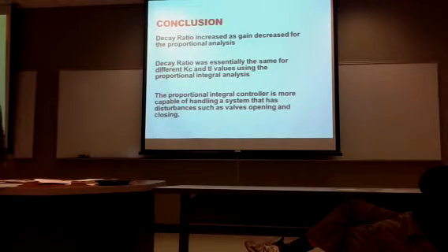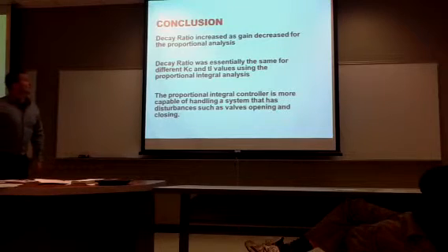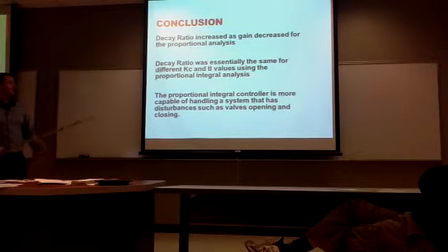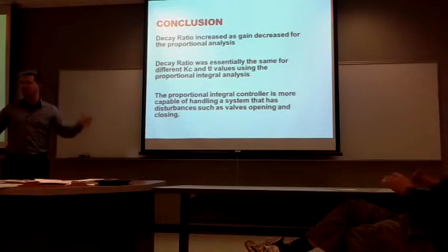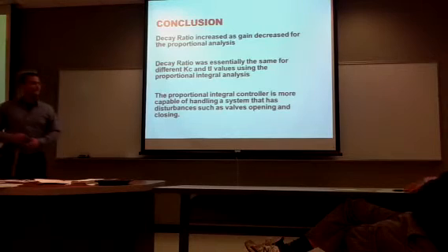So in conclusion, I noticed that the decay ratio increased as the gain decreased for proportional analysis, but during the proportional integral analysis with the different values that I used, there seemed to be not much difference in the decay ratio. The proportional integral controller is much more capable of handling a system that has disturbances, with valves being turned on and off.